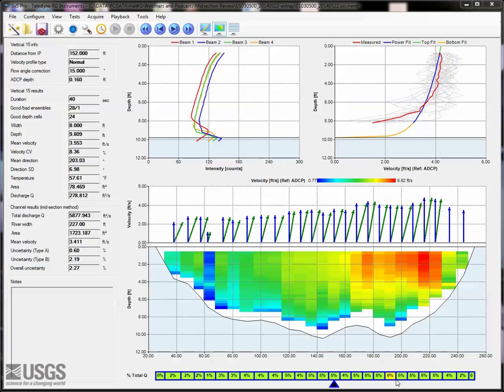When evaluating extrapolation methods for any ADCP data, it is useful to have some knowledge of the site conditions to aid in your understanding of an appropriate extrapolation method. For example, it's useful to know about the bottom substrate type and size in relation to the channel depth, the channel shape, and hydraulic features upstream and downstream of the cross-section.